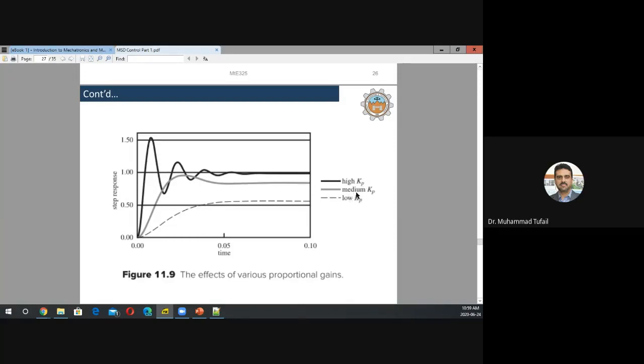And if you bring the value of KP low, then you're somehow getting less overshoots, but you are getting some steady state error. You're not achieving the desired quantity. You're off by some amount from it. And also your response is slow. And if you make it extremely small, the response is extremely slow and you don't even reach there. The steady state error between the desired and the actual is way large. So KP alone cannot achieve the position control.